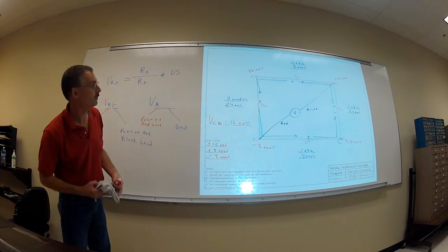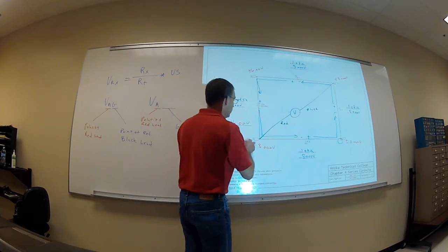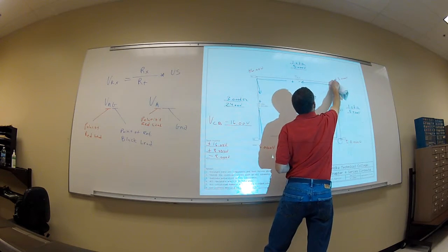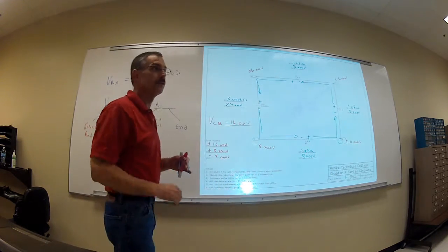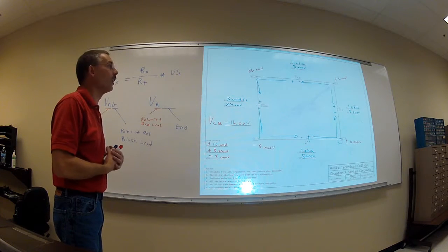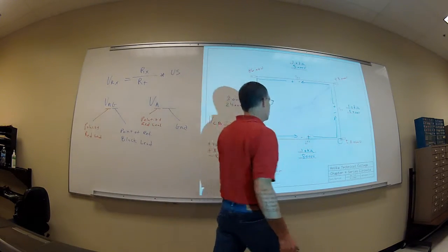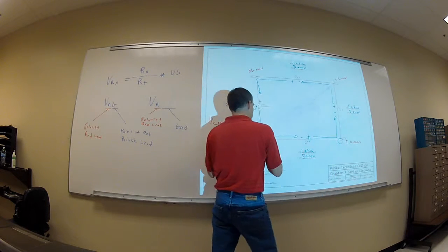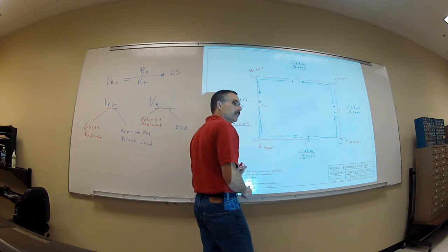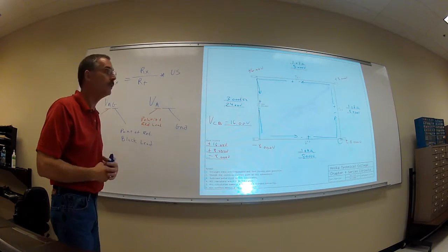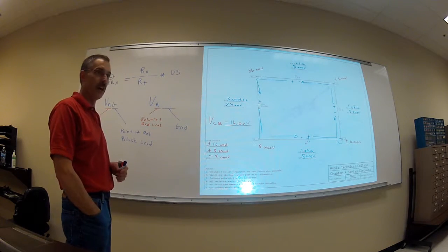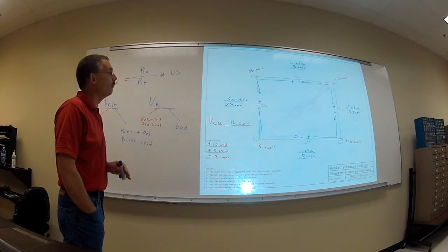Okay, I'm just measuring that potential difference, and I would get a negative 16 volts going across there. We were talking about this in the group, and I wanted to show them that they can measure a negative voltage with an analog meter. With that one, you'd have to reverse the leads in order to do it. You'd have to knowingly know it. That is correct. When you're using an analog meter, I would have to know that this one's going to be more positive, this one's going to be more negative, and then I would have to know in my head to flip the leads around. So you know the rule, but you switch it so that you're reading a negative voltage. Yep, exactly.